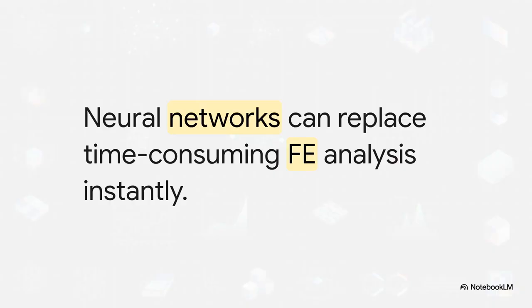So, what is the big takeaway from all of this? Ultimately, it's a massive, validated acceleration in simulation-driven design. The researchers proved beyond a doubt that neural networks can reliably replace that grueling, time-consuming micromechanical finite element analysis of unidirectional composites. By chaining a micro-NN to a meso-NN, they built a truly generalized approach.